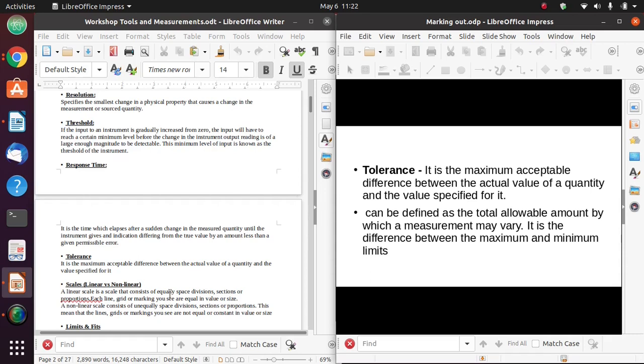Even you as an engineer or a technician or whichever job you'll be doing, a tailor or a shoemaker, you have to ensure that when you're making something, you give that measurement an allowance. You do not cut, say, metal exactly. Specifically, if I want 10 centimeters, I won't cut 10 centimeters.